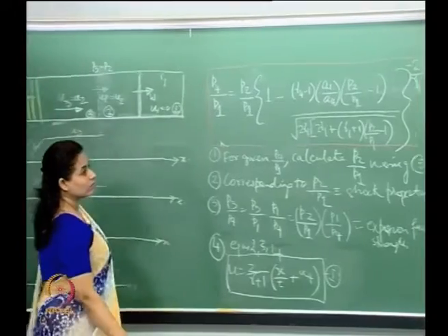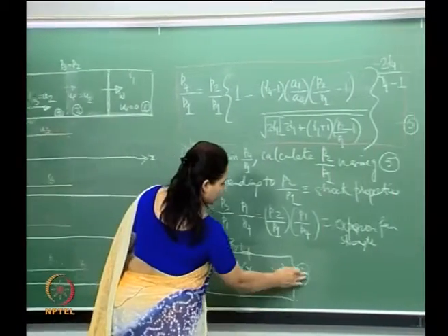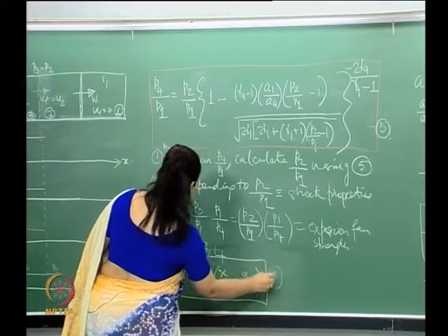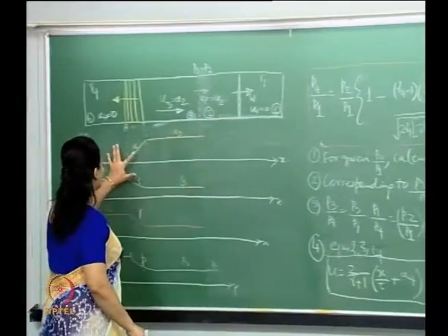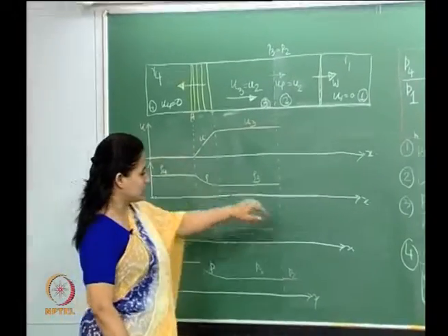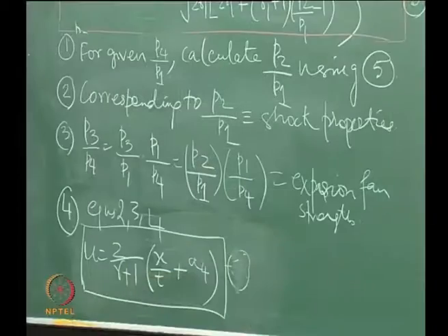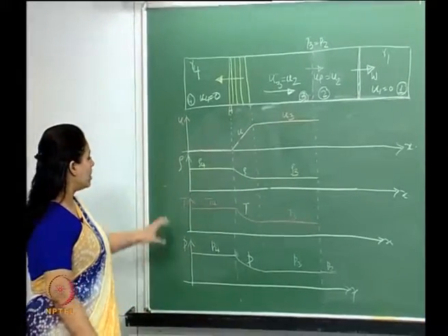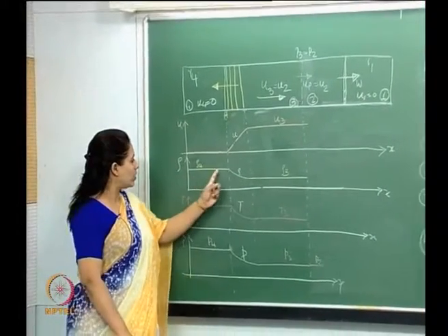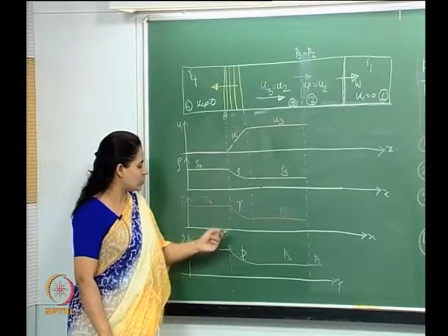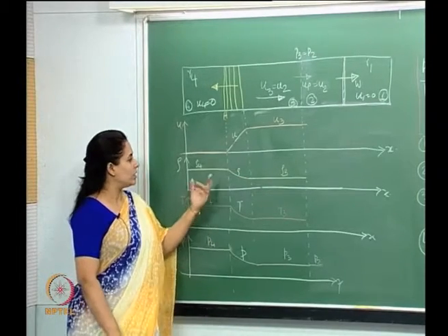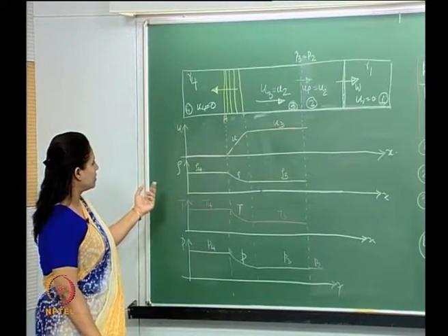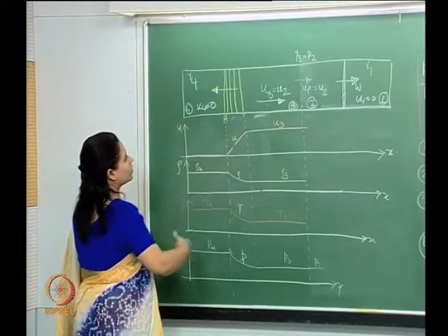the velocity, we plotted this using this relationship, and these are rho, T and P, with equations 2, 3 and 4. Using equations 2, 3 and 4, we were able to figure out the nature of the changes within the expansion fan, and behind and aft of it.